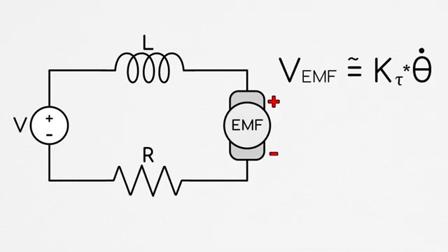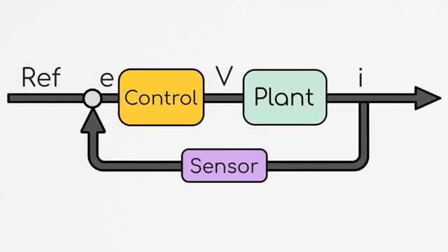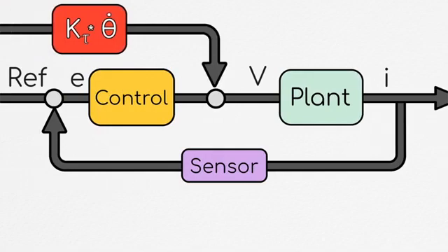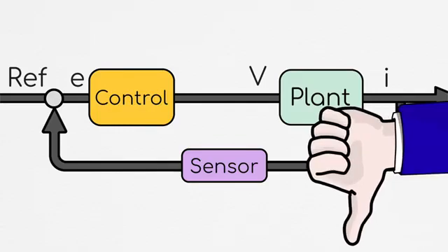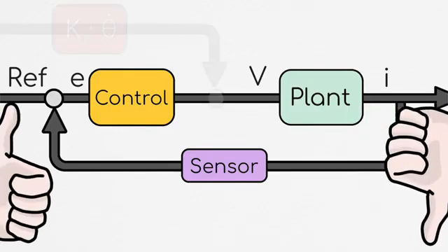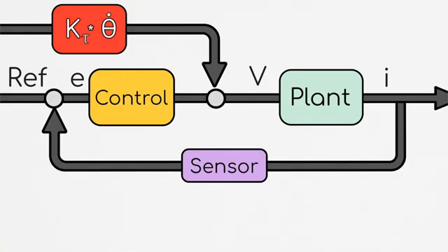With this knowledge and our ability to get a slightly noisy approximation of velocity from the motor's outer control loop, we can thus add in a feed-forward term which is a function of the rotation rate of our motor. In doing so, we can mitigate any issues that this back EMF term would cause in our controller. This often isn't necessary, but for some systems that are turning very quickly and non-constantly, it's a good approach if feedback control alone isn't producing adequate results. So that's the basics of designing your motor controllers.